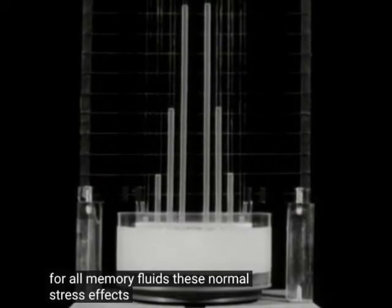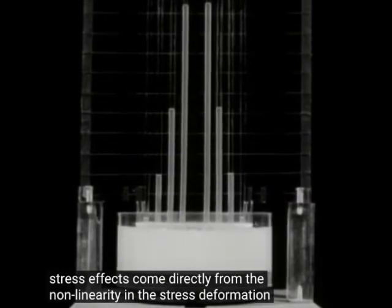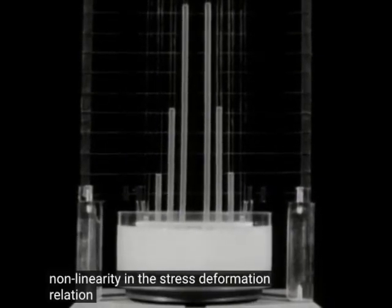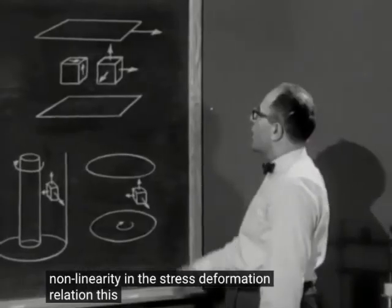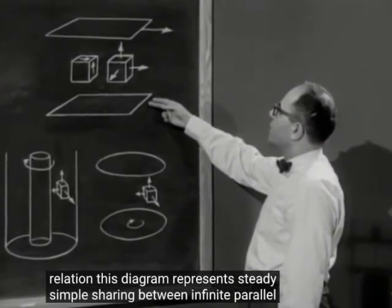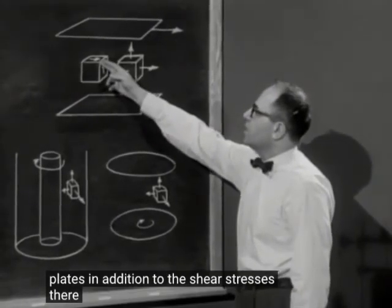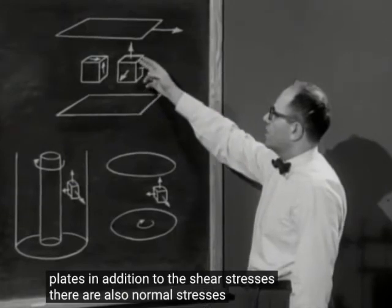These normal stress effects come directly from the nonlinearity in the stress-deformation relation. This diagram represents steady, simple shearing between infinite parallel plates. In addition to the shear stresses, there are also normal stresses.